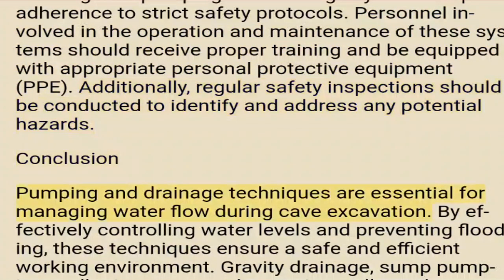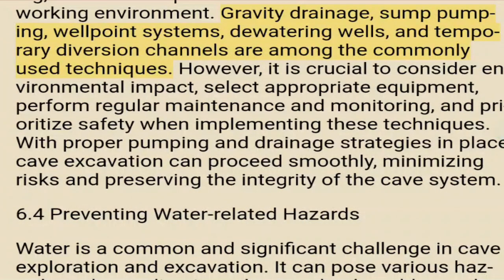Conclusion. Pumping and drainage techniques are essential for managing water flow during cave excavation. By effectively controlling water levels and preventing flooding, these techniques ensure a safe and efficient working environment. Gravity drainage, sump pumping, well point systems, dewatering wells, and temporary diversion channels are among the commonly used techniques.